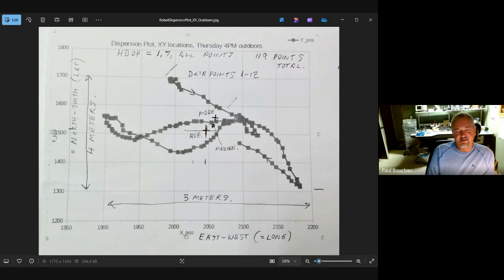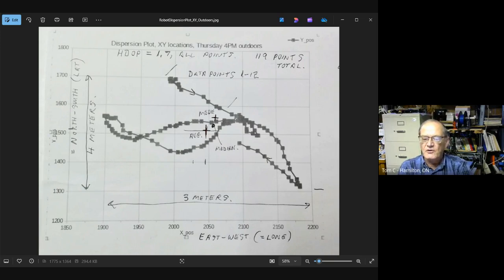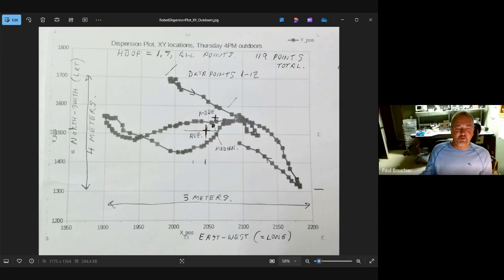Fundamental assertion that if it doesn't wander much between successive readings, then it could be reasonable to take your direction of motion from two successive readings. Yes, except that these tests are always done when you want to find out how much wandering is happening. These tests are typically done when your robot is stationary. So I don't know that the wandering would look like that while it was moving. Paul, the real question is, how far does your robot go in 1 second relative to this potential error? Right. And the magnitude of that 30 centimeter jump between 1 second readings gives me pause.